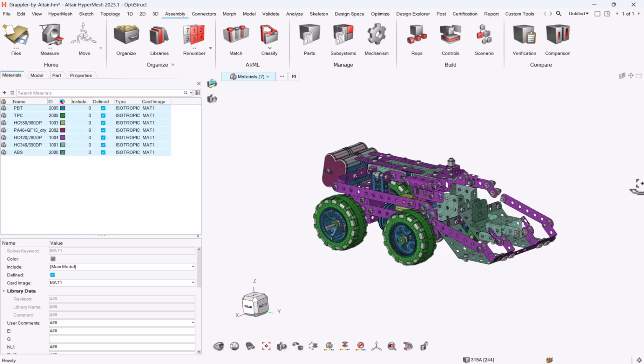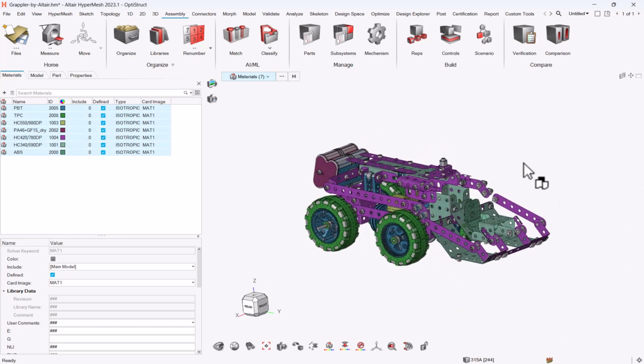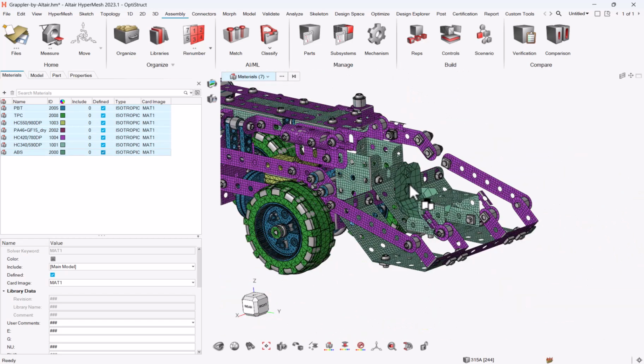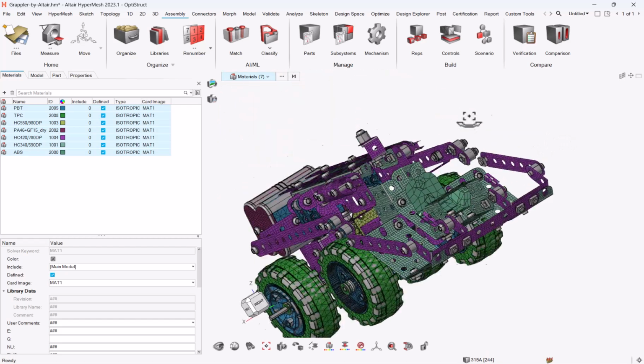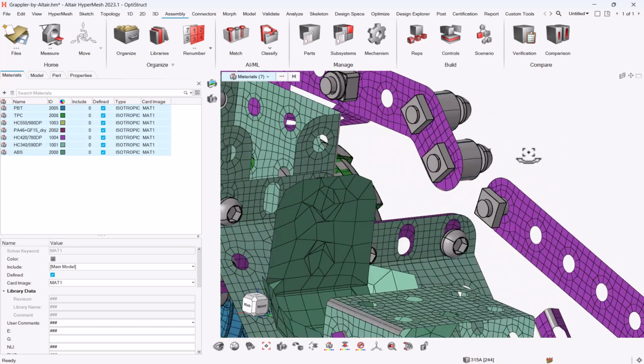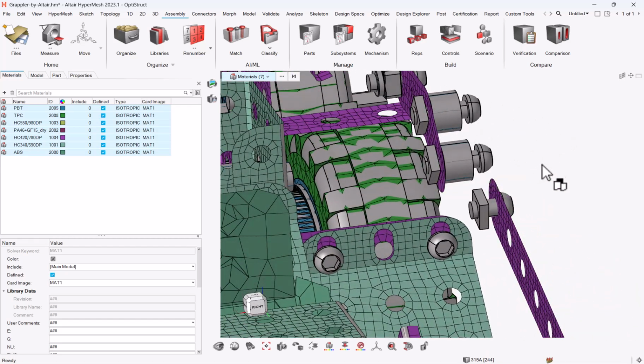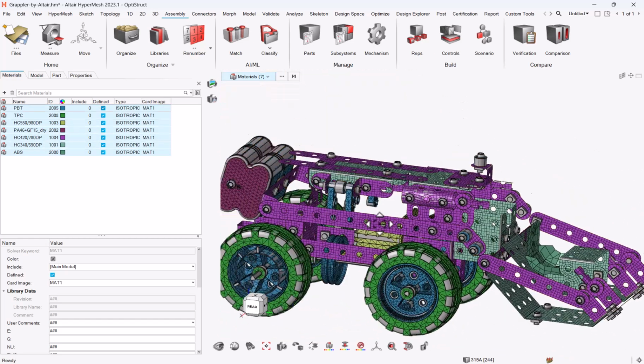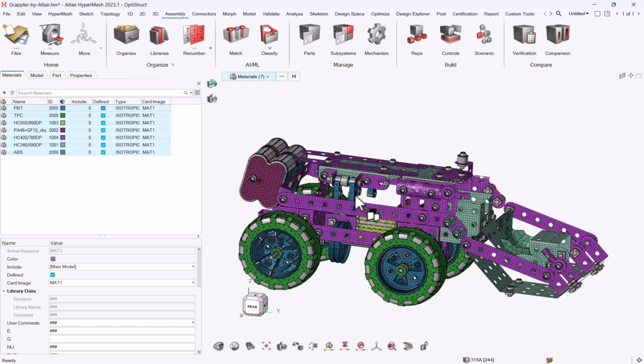So as a conclusion, you can really use Part Browser to streamline your first, preliminary mesh. Once it is done, you can review by material type or whatever to check the quality of your mesh and possibly fix any part. Here the Midmesh, for instance, I could work on again. There are probably some other parts where I need to figure out why the mid surface failed, but there are many parts which are meshed where I don't need to review anymore.